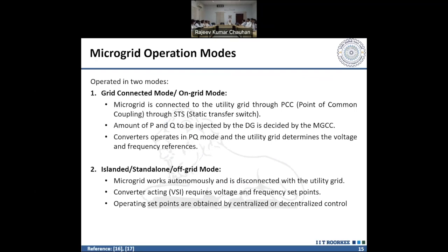Even if your load is drawing real power, which is supplied by the generator, there is still a reactive power change, reactive power draw, appearing in the system, which is the major cause of the voltage drop. And the major cause of the drop in frequency is the real power. So these two things we have to control at the generating stage.